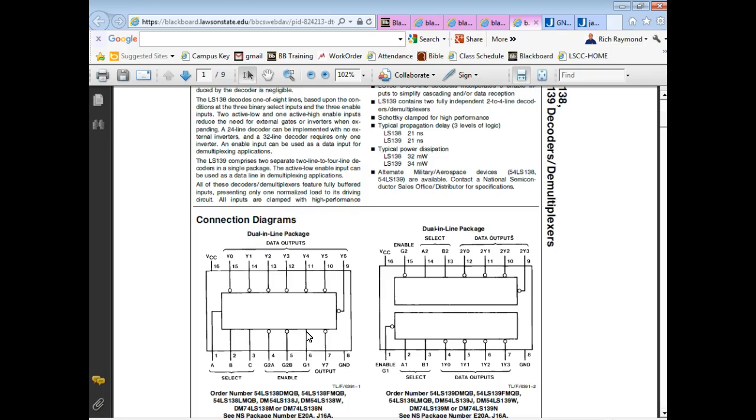So a decoder would be like you sitting here looking at some lights. This is the address bus, and all you're set up to do is recognize a certain pattern of ones and zeros. When your pattern comes up, you reach over and open a mailbox. And once the mailbox is open, you can do what? You put stuff in it, or you can get stuff out of it. If your pattern is not on the address bus, then you do what? Your box is closed. So how do we open these mailboxes, and how do we close them? Well, we open and close them with these enable pins.